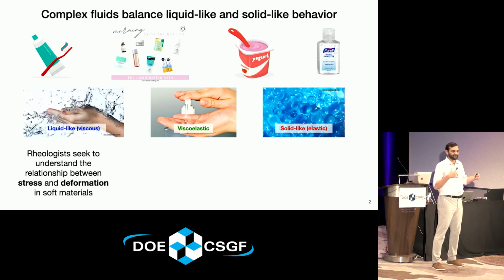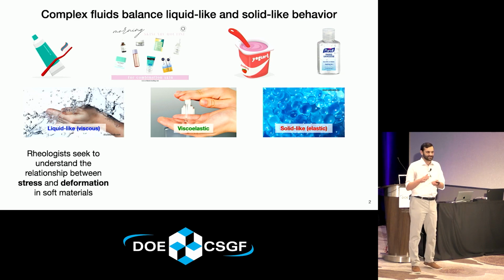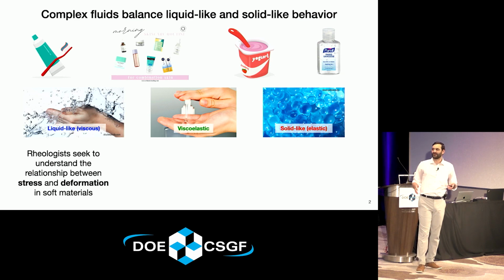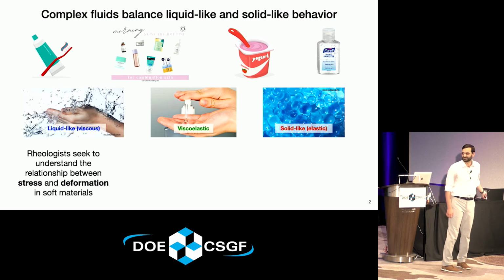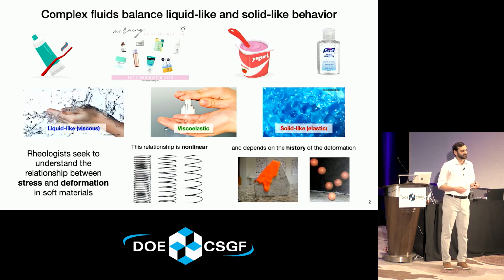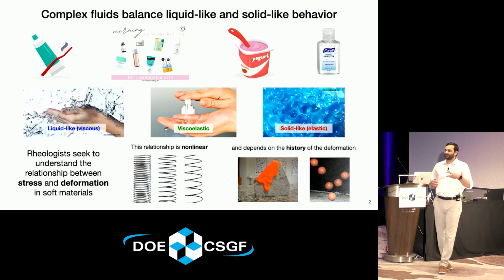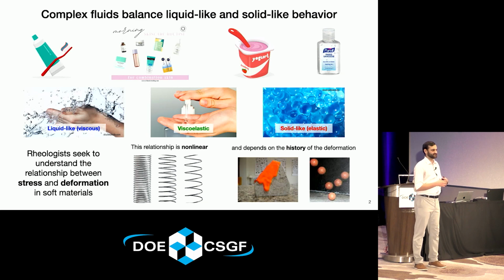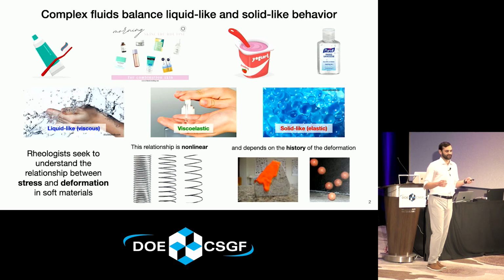And so that's sort of the purview of this field of rheology, to understand the relationship between the stresses that we put in and the deformations that we get out in these complex fluids that are somewhere between a liquid and a solid. What makes this relationship so complicated and worth an entire field of study is that firstly, it's nonlinear, and secondly, it has this interesting property where the properties of the material at a certain time sort of depend on what's been going on in the recent past to the material. And really this results in very different looking properties based off of the time scale that we observe our materials in or that we deform our materials with.